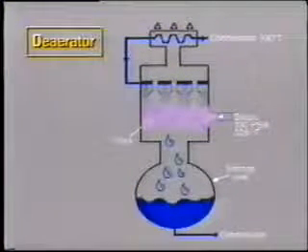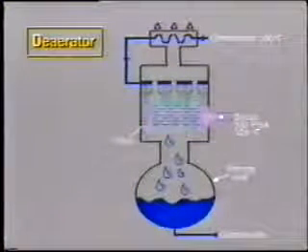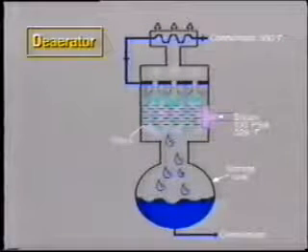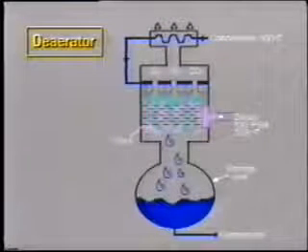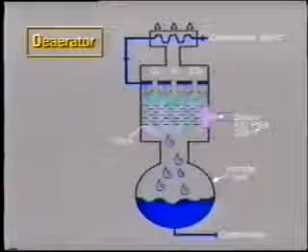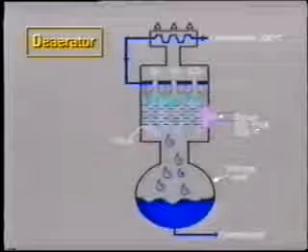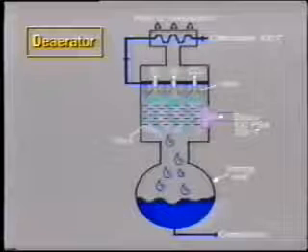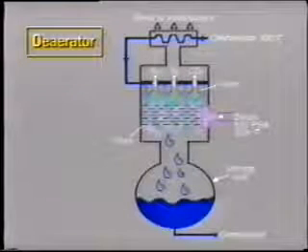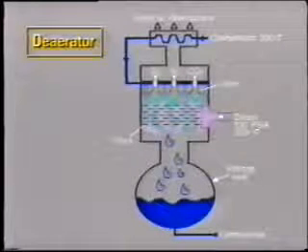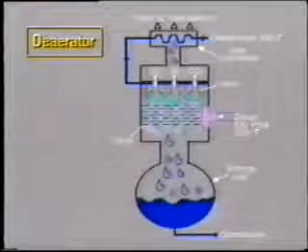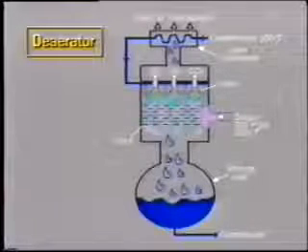The result of this agitation and increase of temperature enables most of the incondensable gases, such as oxygen, nitrogen, and CO2, which are dissolved in the water, to be liberated. These gases are expelled through vents at the top of the de-aerator. Some steam may try to escape with the gases, but this is condensed in a vent condenser, which employs incoming condensate as the coolant.